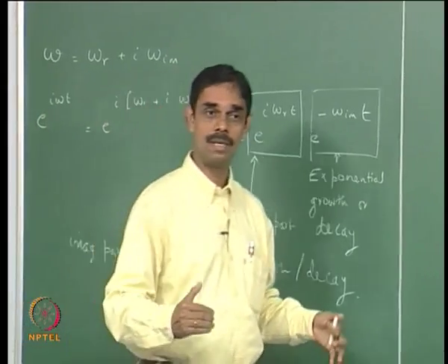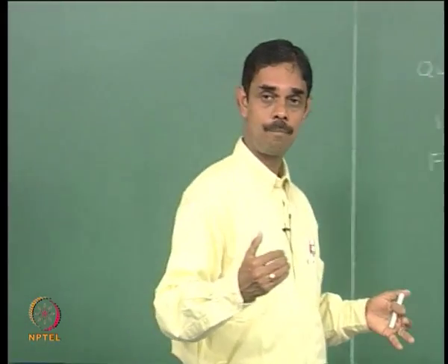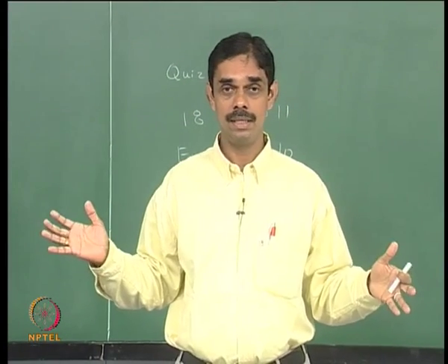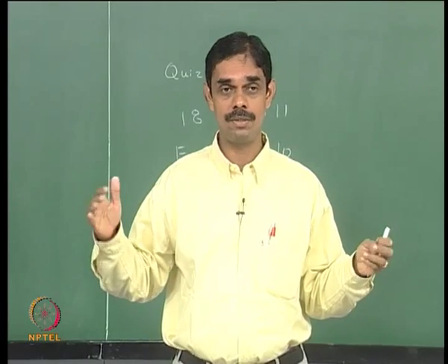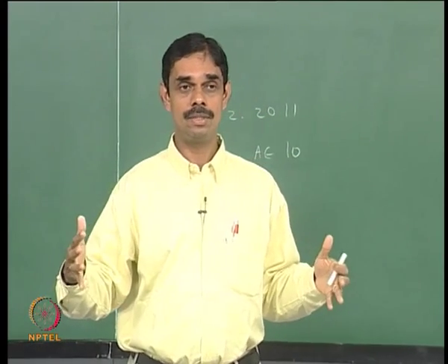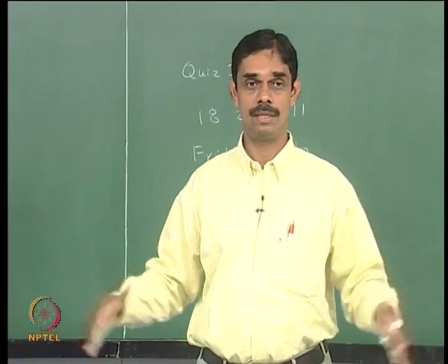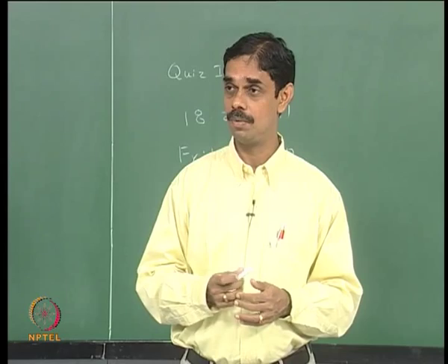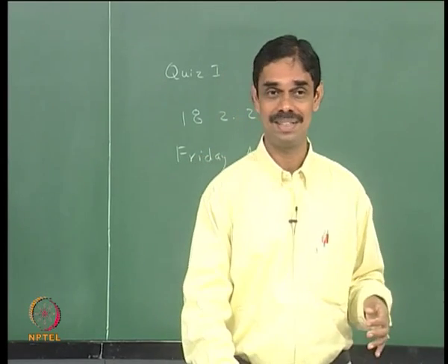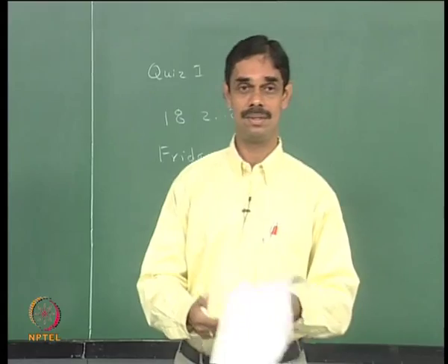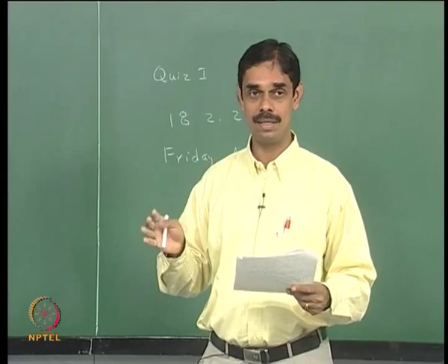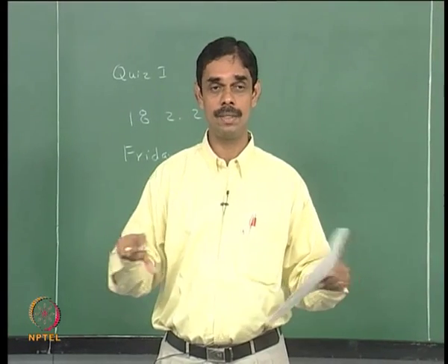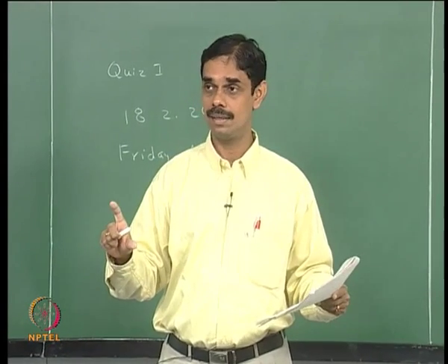So we will do it in two steps. First we will deal with how to determine the admittance of a termination using this impedance tube technique. That is essentially a forced experiment. You force the sound with a loudspeaker, and then we will see if we can translate it into some kind of self-excited problem where you leave a system alone and see what happens. I hope this approach is clear. It sounds a little crooked, but once you work it out you will see it is not all that crooked. In this process we are doing the experiment with the loudspeaker at a real frequency, which means we are setting up the experiment in some kind of steady state. Is that clear?